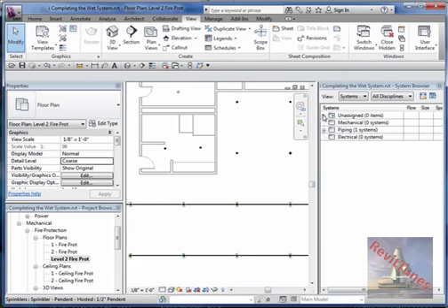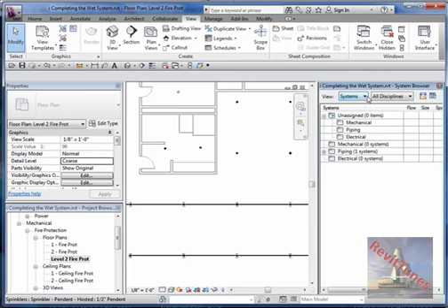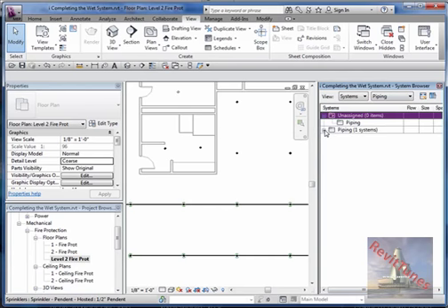And if you go over here, I'm going to show disciplines only piping. Okay, remember before we had so many sprinkler heads unassigned here because they didn't have a system. Now after we assign them to the same system, number one, now all those heads are right here.